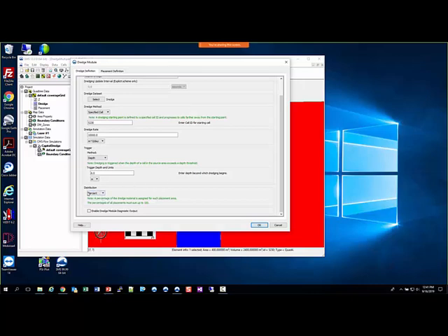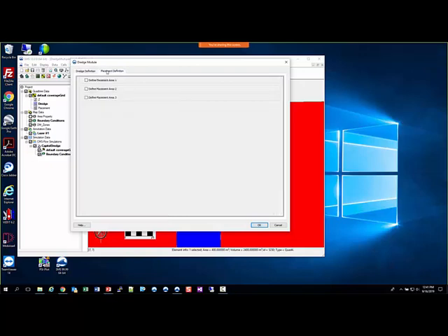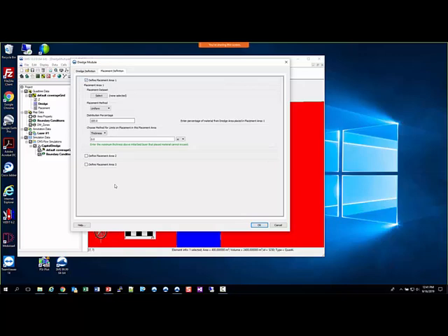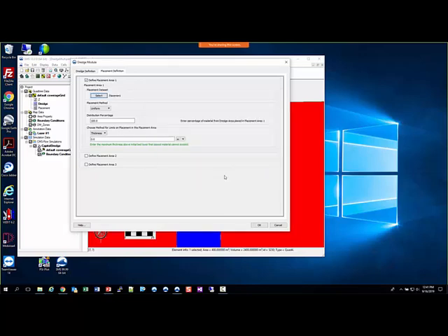We're distributing it as a percentage. And as it says, all the placements must sum up to 100. There's some extra output that you can turn on or off if you need it. By default, it's off. So we've got that set. We can go over to placement definition now, and we will turn on placement area 1 and select the data set, which we're going to use to define that area. So that's placement. Click OK, and it shows up here.